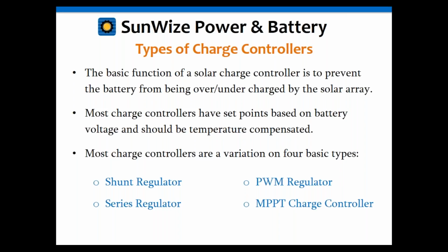That being said, one of the most important features of a charge controller, although I still will not go into features, I will mention one: temperature compensation. It really should be there. It's very important to have that. The battery voltage should be adjusted for temperature. In other words, when it's cold out, the battery will be charged more. When it's warm out, it will be charged less. If you do not have that, your battery will not get properly charged, and it could fail prematurely.